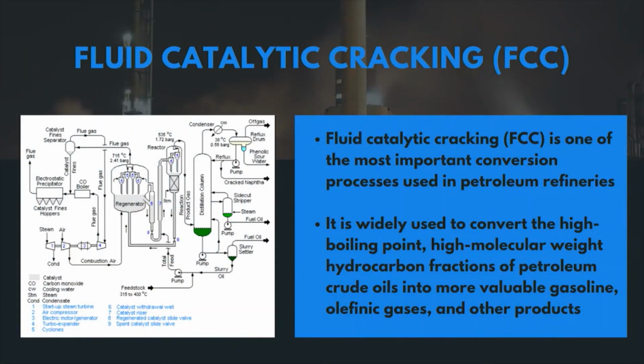Then the next unit is known as the fluid catalytic cracking unit, or in short FCC or FCCU. Here the residue is heated and then undergoes chemical reactions in the presence of a catalyst. The catalyst consists of fine solid particles, and these fine solid particles are in a fluidized state.